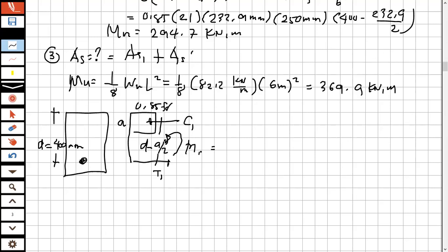Okay. Dapat itong M1, it should be that sa doubly reinforced beam, pagka small siya sa MU mo, ibig sabihin, this one is not enough para mag-resist sa MU. Your MU here, yung calculated na MU natin, is 369.9 kilonewton meter. Pagka yung M1 mo, yung internal moment mo, is smaller than that, magko-collapse yung structure mo. So, kailangan dagdagan mo siya ng M2. How you do that? You add additional reinforcement here para masatisfy niya yung need ng 369.9 kilonewton meter.